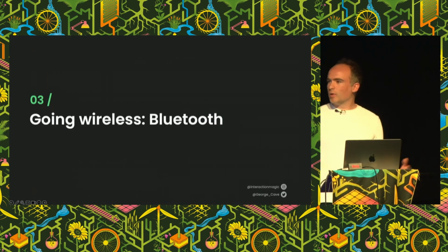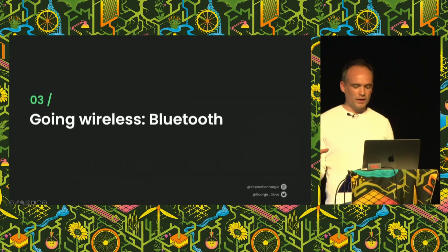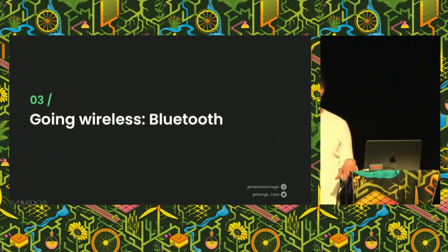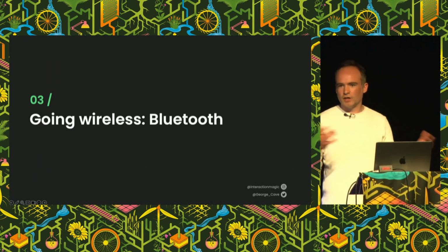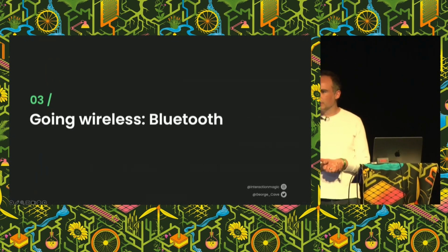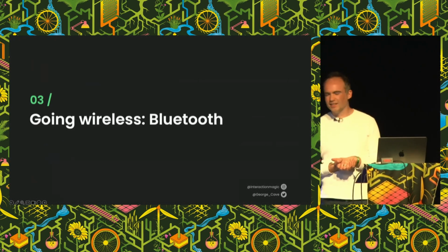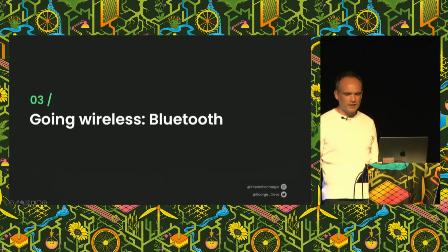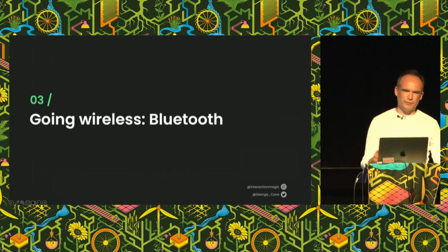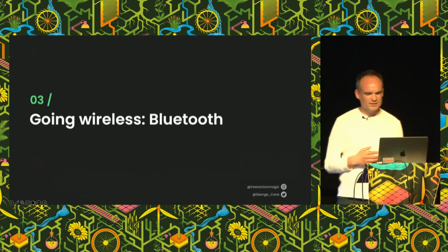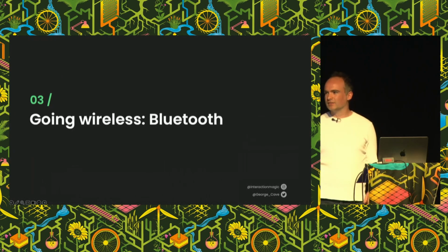So keyboard emulation and web USB are a lot of fun, but the real magic is when you make things connect wirelessly. There's a few ways to connect to an Arduino wirelessly. Obviously, there's a whole family of really popular ESP Arduino boards. A lot of them predominantly use Wi-Fi, but I find Wi-Fi very messy. You're always fighting with access credentials when you change locations. Certificate handling is really hard for HTTPS and stuff. And it's also quite power intensive for battery stuff.